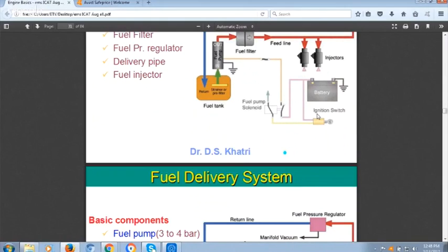But there may be a need to design a variable speed fuel pump. All these things we can understand when we go deeper and deeper. But I am giving an example: suppose a Swift car, 1.3 liter, the flow rate is around 80 liter per hour. And the maximum requirement never goes more than 6 liter. So the fuel flow rate is 70 liter extra.